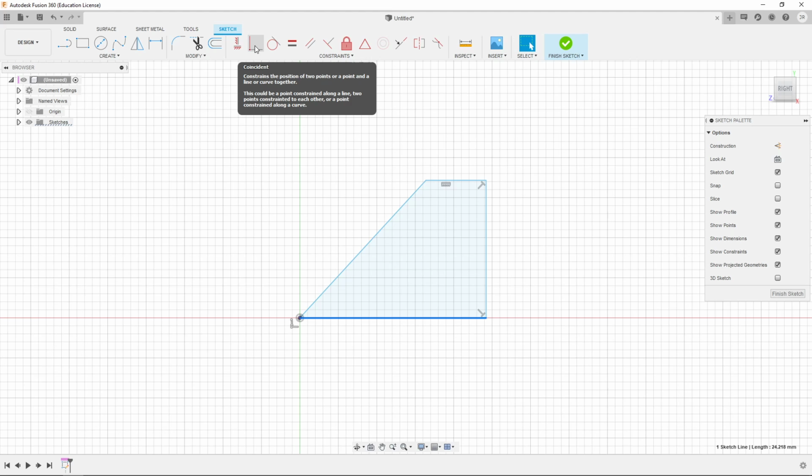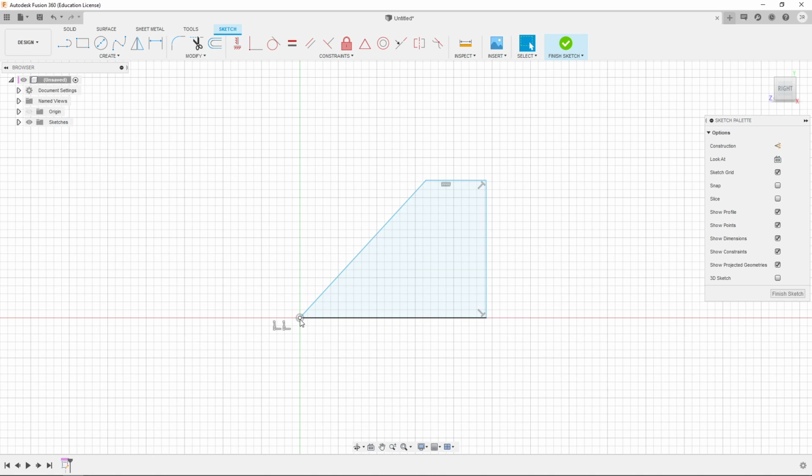A line is two vertices connected by an edge, right? So a shape is multiple lines where all of their vertices are coincident at some point. So there are actually two vertices here, this one from this line and one from this line, and they are coincident with both each other and the origin. So I cannot move this point. If I try to drag it, nothing happens. It stops me. It says, nope, you are locked into place.